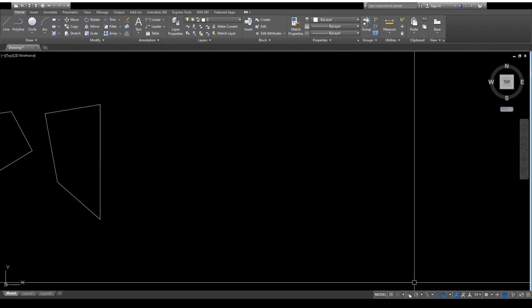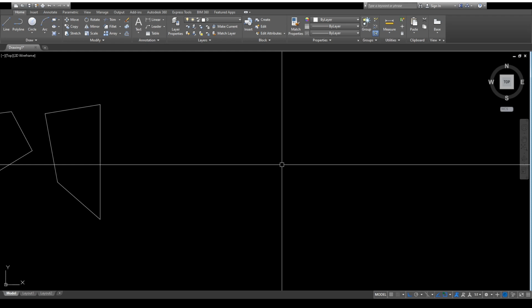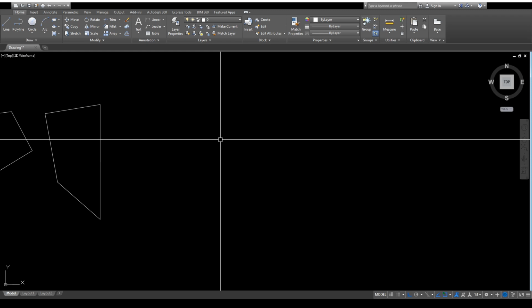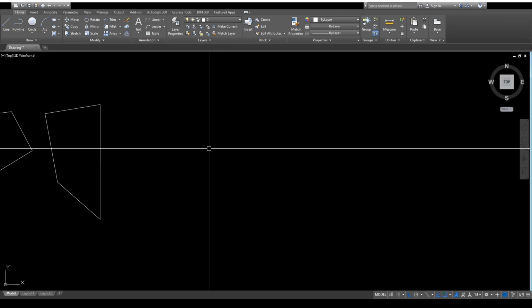Ortho mode. Ortho mode, ang ibig sabihin niyan is orthographic drawing. If you remember during your first years in college, in architecture, meron kayong orthographic drawing. Ang ibig sabihin niyan, lahat ng lines na idodrawing ni AutoCAD ay 90 degrees. Para mo na ring sinabing may T-square at saka triangle ka at 90 degrees lang ang kaya niyang i-drawing. So, 90 degrees as in horizontal or vertical.